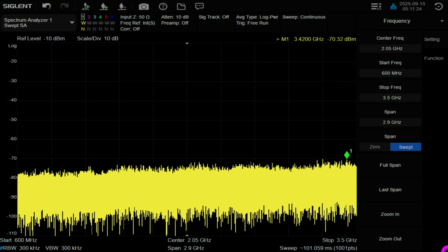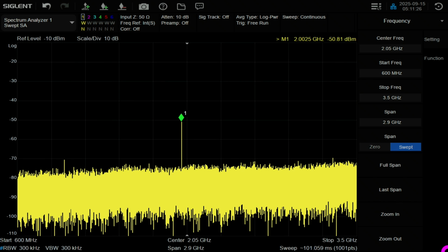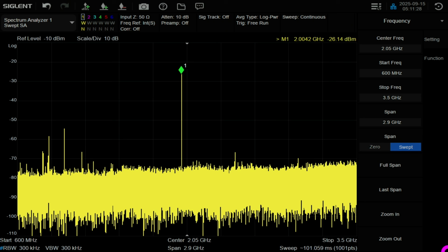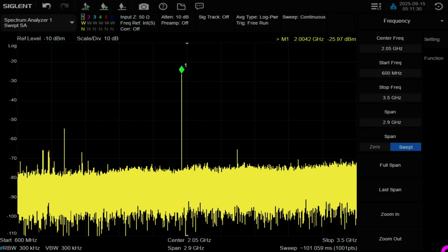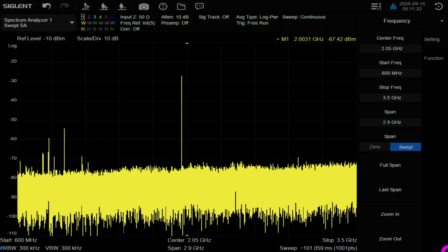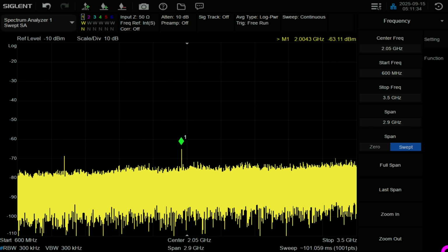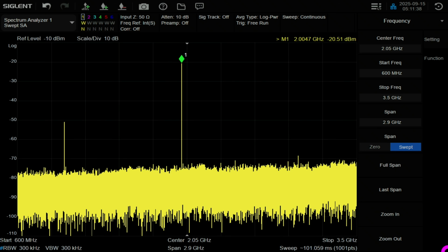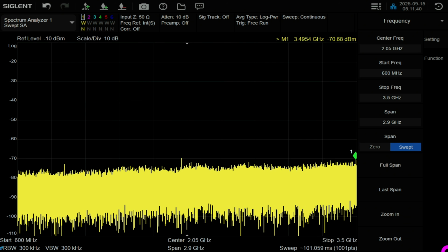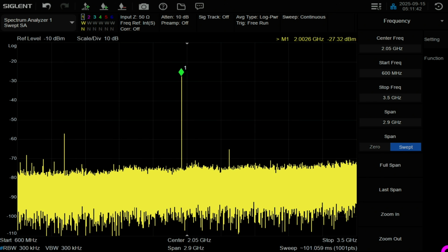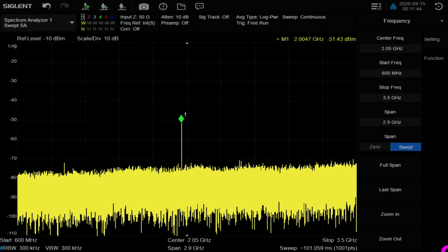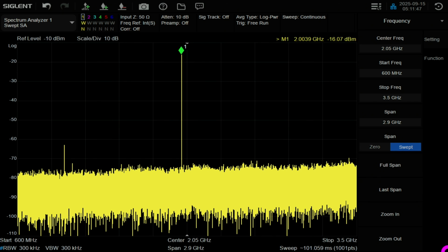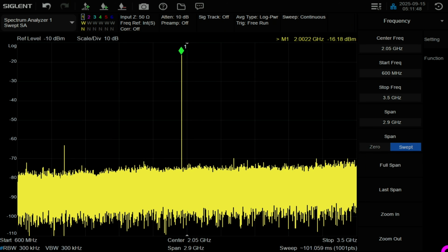Now does that reach all the way to the input of the divider? Yeah, there it is. The input of the divider is also there. The signal is quite a bit smaller. There's a lot of loss there. I'm guessing that's normal. So what do we have right before here? It goes from -20 with a long trace in the PCB to around, yeah, my grounding is not perfect. No, it's fine. There's a little bit of loss, but it's not too much.